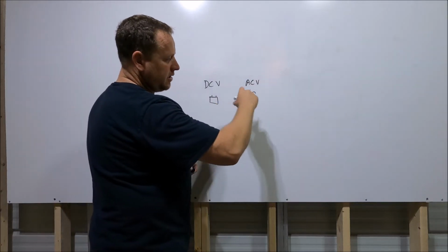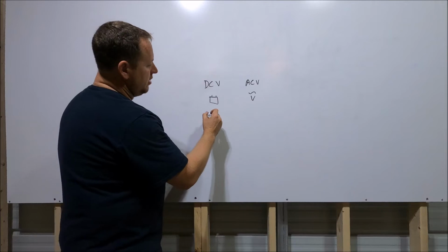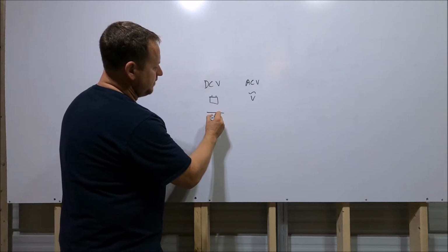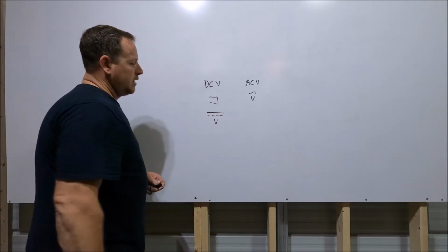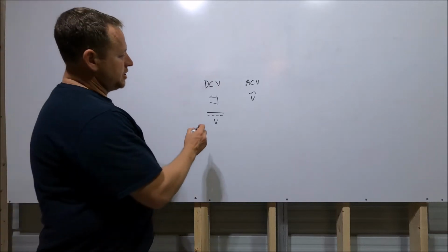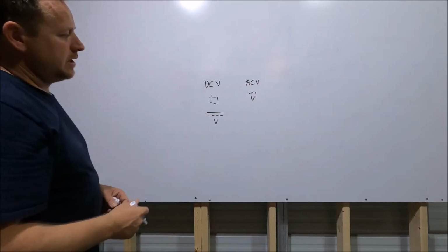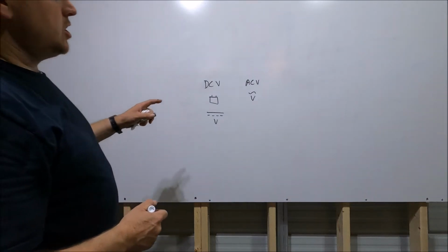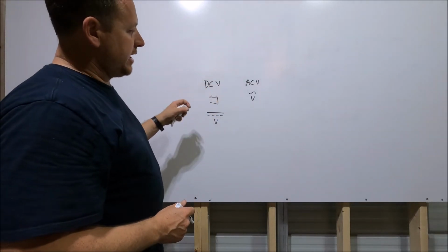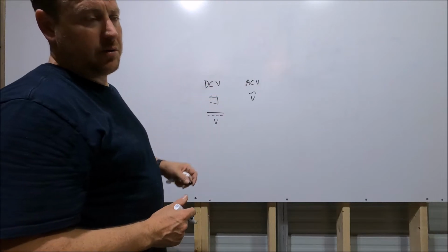That's your oscillating current, your AC current. You'll also see something like this on some voltmeters. This just shows that instead of it being a squiggly line, it's direct current. So you want to make sure that whatever system you're analyzing, you have the setting right on your voltmeter.